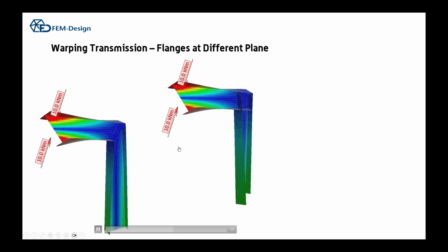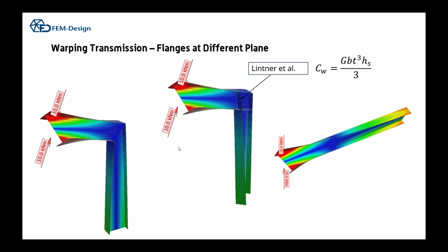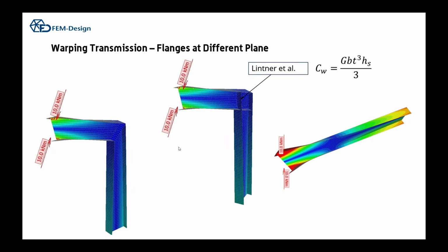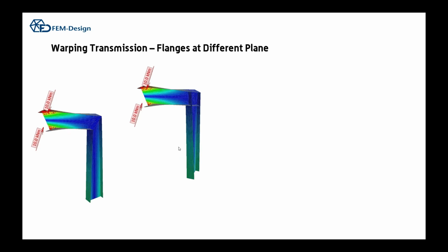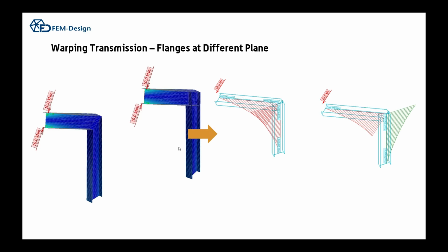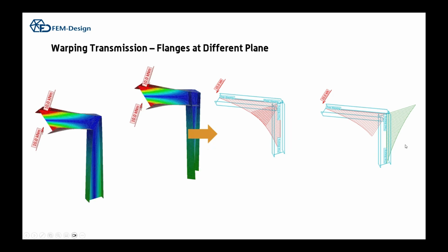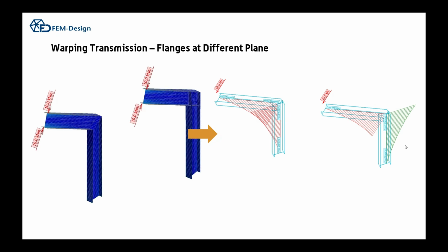And this is really hard to calculate, but how you can think of it in reality is that maybe there's a stiffness which will dissipate part of the warping. But if you want to be practical, let's think about how we can flip the bimoment. By applying a negative spring value in the beam end, the bimoment will flip and the warping direction will flip. It's really illogical, because a negative spring value in the beam connection in the classical 1 to 6 degrees of freedom doesn't mean anything.